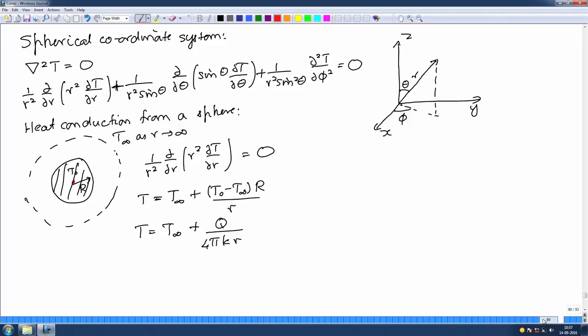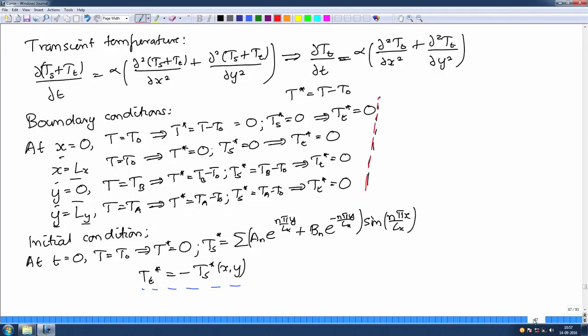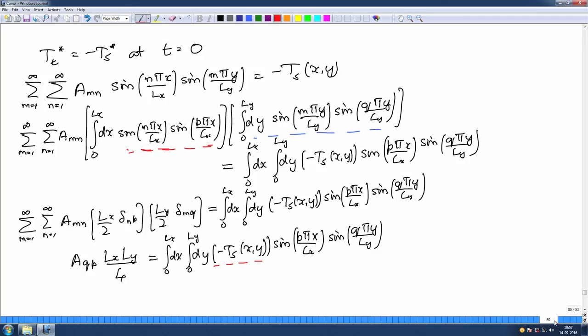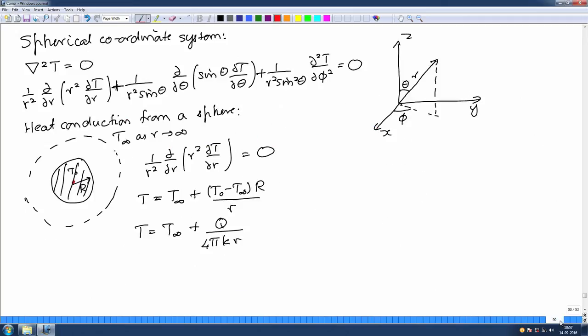So, welcome to our continuing discussion on diffusion dominated transport. As I had told you in the previous lecture, diffusion dominated transport refers to the case where the Peclet number is small or the Reynolds number is small. So that effectively you are solving for a Laplace equation or a Poisson equation for the temperature field or for the concentration field.